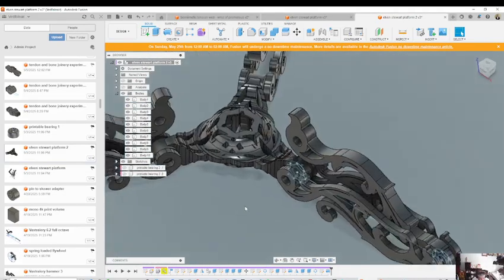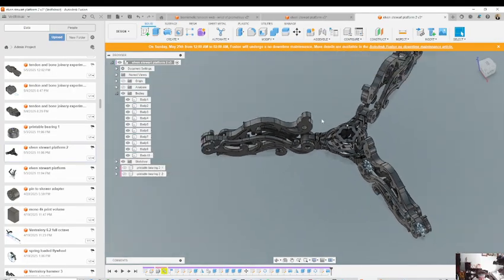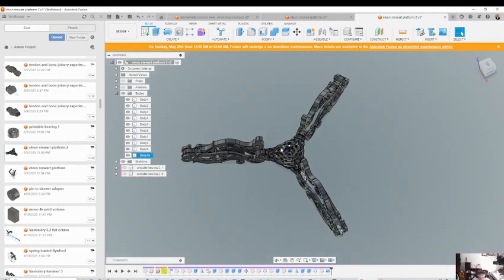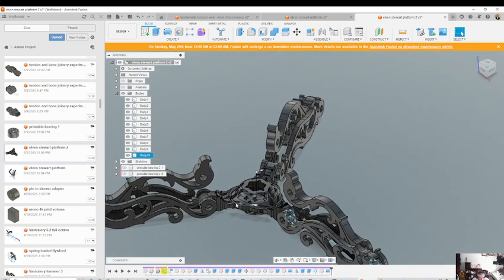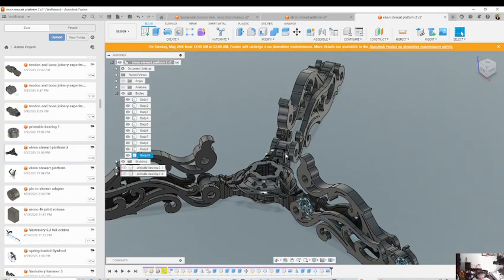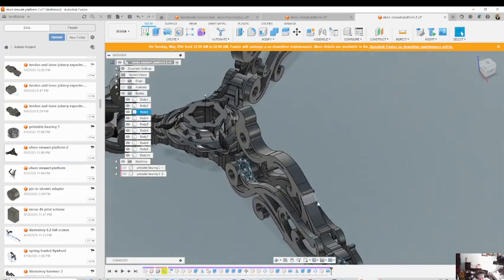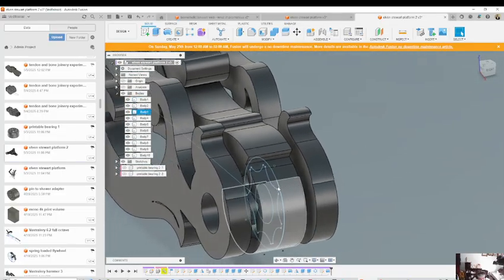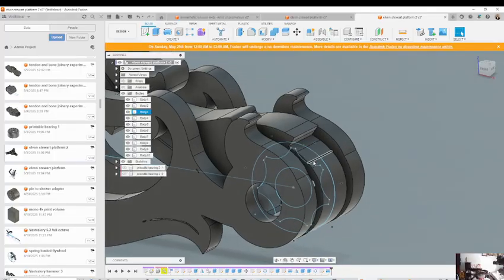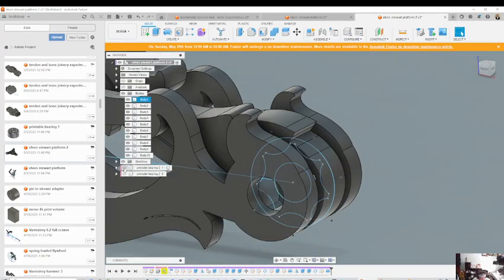Now, I could have embedded a 3D printable bearing at the base, but it would not fit on my printing platform very accurately unless I made some significant changes. Well, I could, but I decided not to go through that. So I decided to keep the central part with a skewer connection here, but I did employ a printable bearing in the connection of the arms here. So you can see the fluted pattern that was derived from the printable bearing.